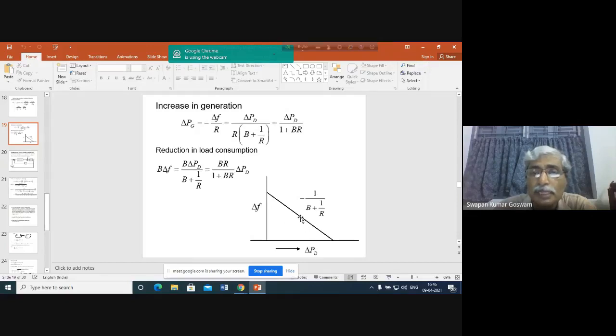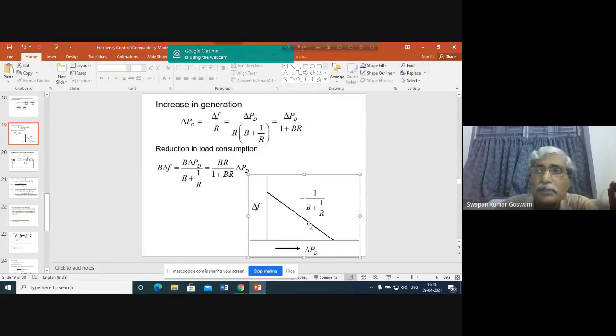Now it means that after you have increased the demand, say here, load has been increased up to this point, then this should have been the operating frequency had there been no change in the speed changer position. Now, with the change in the speed changer position, what you can see, delta f becomes 0. That means frequency is coming back to this position, normal steady state.